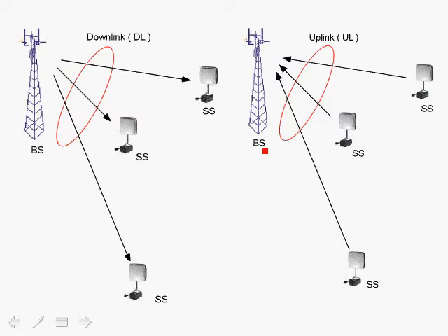I will go in depth and describe how this is done in 802.16a, and we will also discuss how power management is achieved. Another issue that has to be resolved is the effective frequency offset. Every subscriber station might have a frequency offset compared to the base station, and the frequency offset from substation to substation is different. So that is also part of the synchronization process, in the sense that through some mechanism and algorithms, the frequency offset has to be compensated between the subscriber stations as the base station receives their packets.